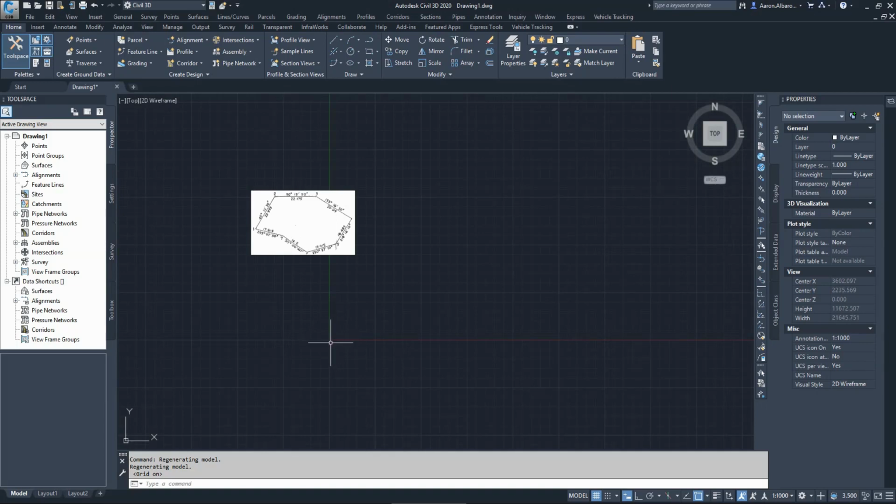Okay, so in order to do that, first of all, to draw this, I need to choose a polyline as a starting point. Later on that polyline, we can change it to alignment, we can change it to boundaries, anything that we want. But as a starting point, a polyline is easier to work with. So I chose the command for polyline, the same as an AutoCAD command.